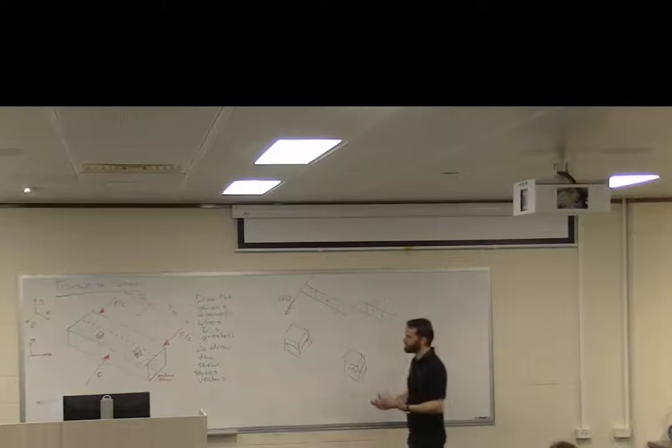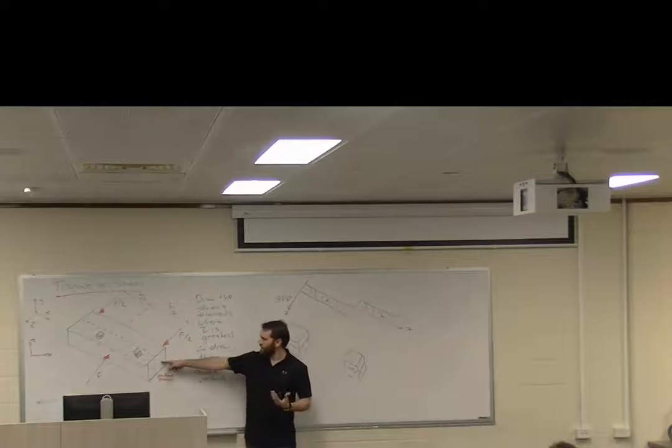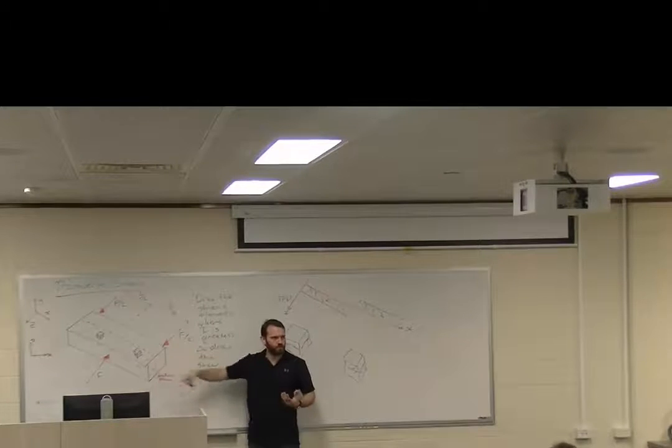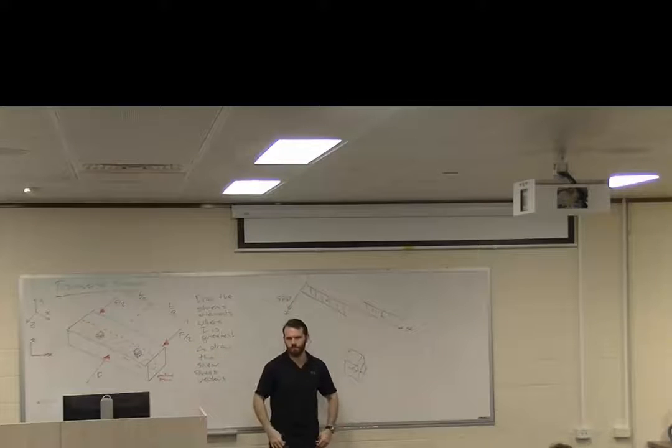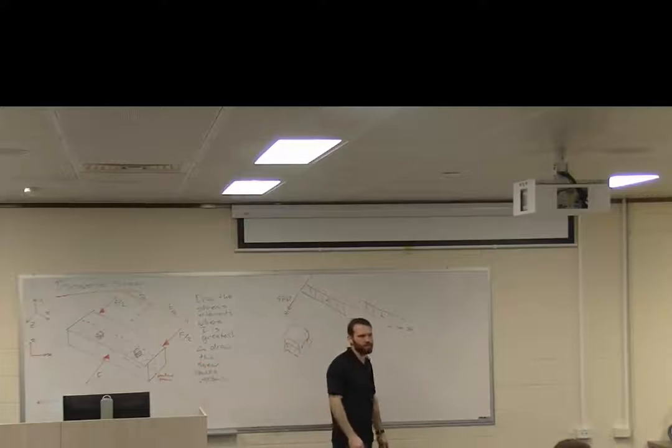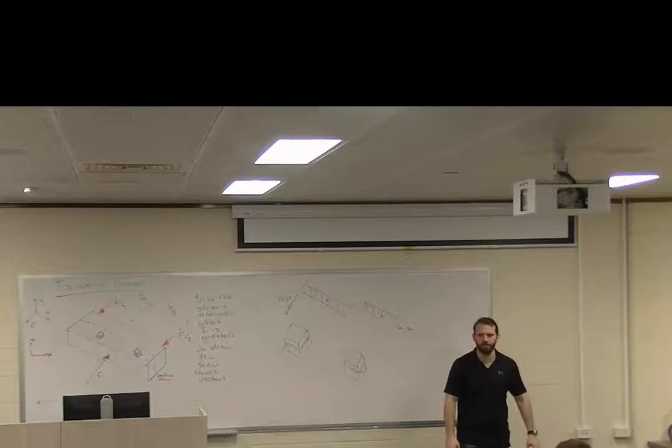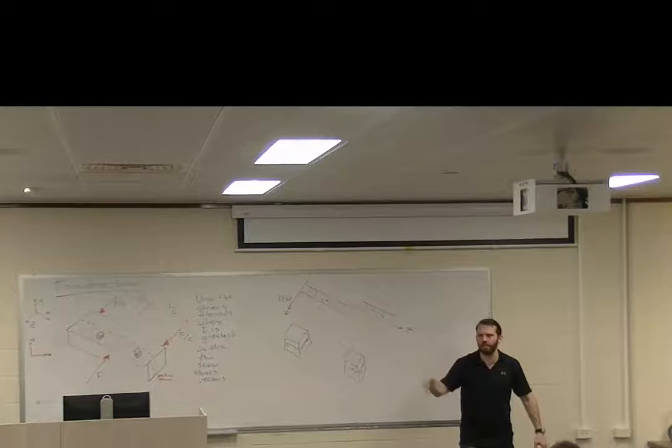Alright, so with a bar like that, in this plane, you don't need force, force, force. You can have 5 forces. Put 5 forces on it, make sure they balance, so sum of the forces equals 0. Put 5 forces on it, do this, and give me a shear stress element at the division between each of those forces. That's a really good study problem.